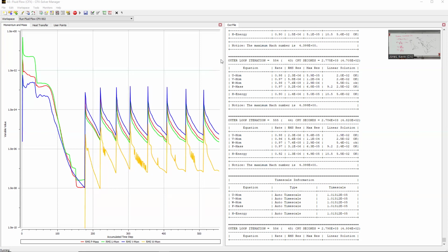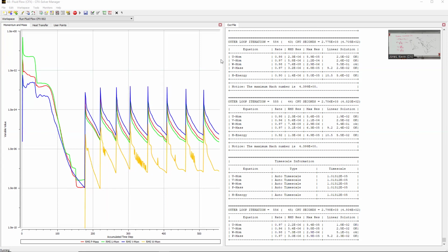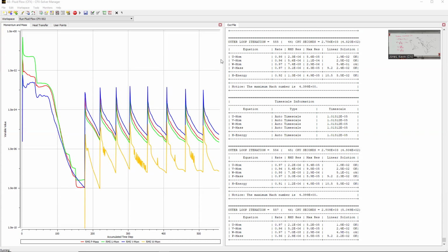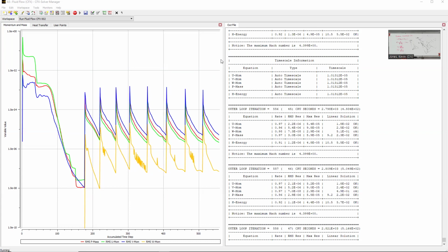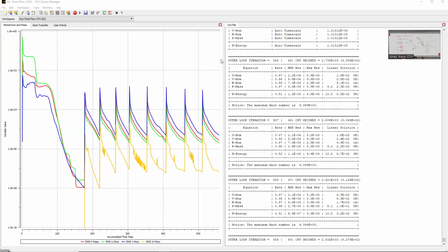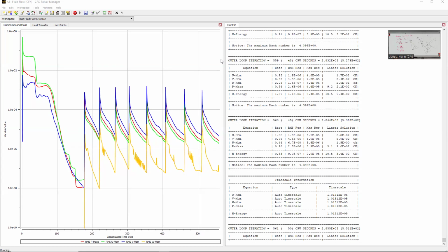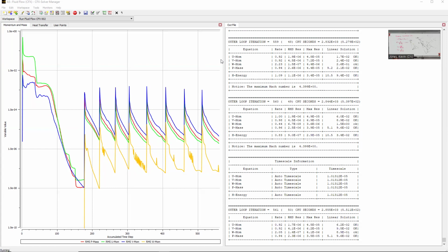This has none of that. It doesn't know any of the equations that are in that calculator. It's solving Navier-Stokes, and it just happens that the shock falls out of the Navier-Stokes equations. But when you do these finite difference or finite volume methods, they always are going to smear. They can't do a discrete change. They're always going to smear stuff out.